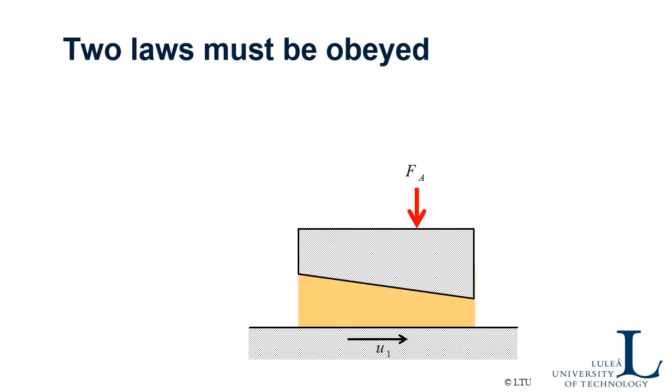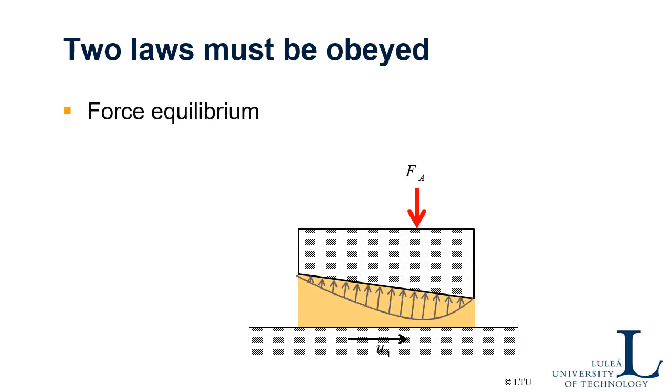In order to answer the question, I will discuss the mechanisms of hydrodynamic lubrication and the wedge mechanism. In mechanics, we have two laws that must be obeyed. Those are, first of all, the force equilibrium. There will be a pressure in the lubricant film, and that pressure must balance the applied load.